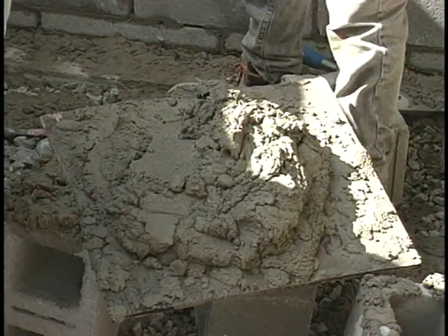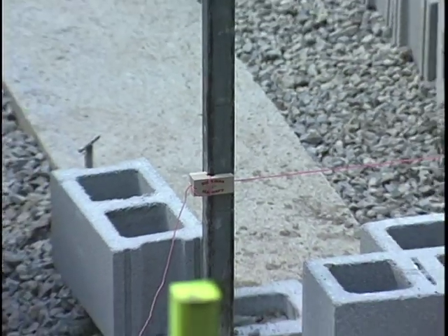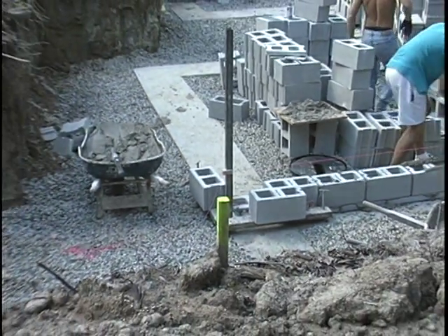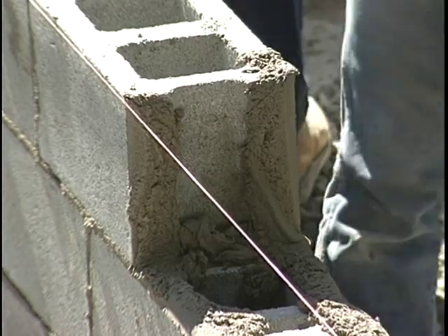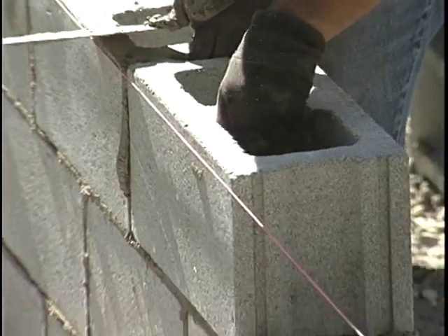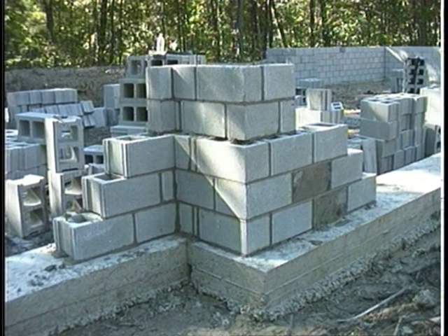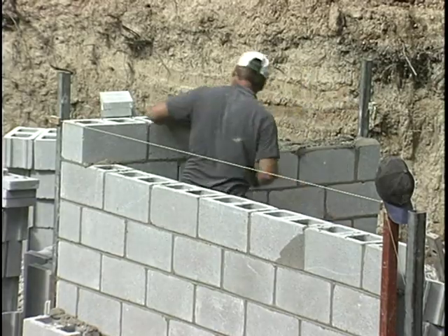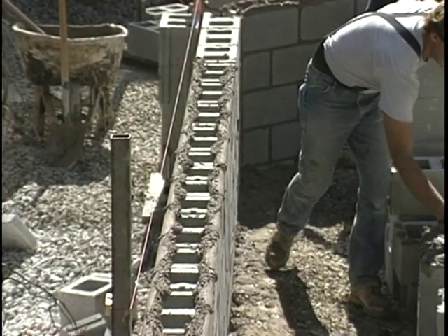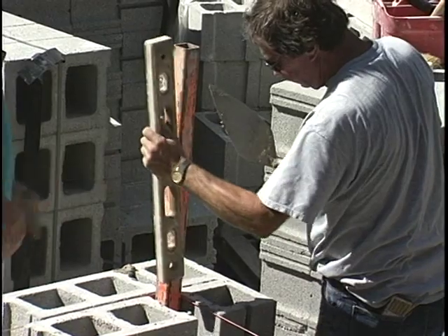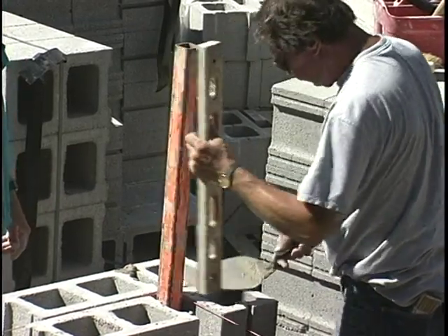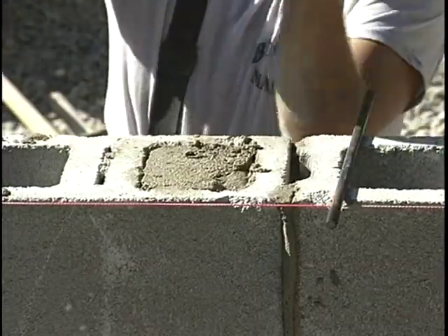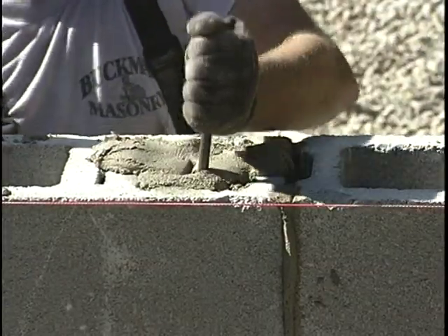Next, lay a mortar bed on the footing for the first course of blocks. Corner blocks are laid first. Head joints on the side of the block are buttered before the block is laid. The corners are usually built up first from 4 to 6 courses high. All corner blocks must be at the right height, in line, level, and plumb. The mason will use a level to check this after laying every 3 or 4 blocks. Block foundation walls must also be topped with anchors to secure the sill.